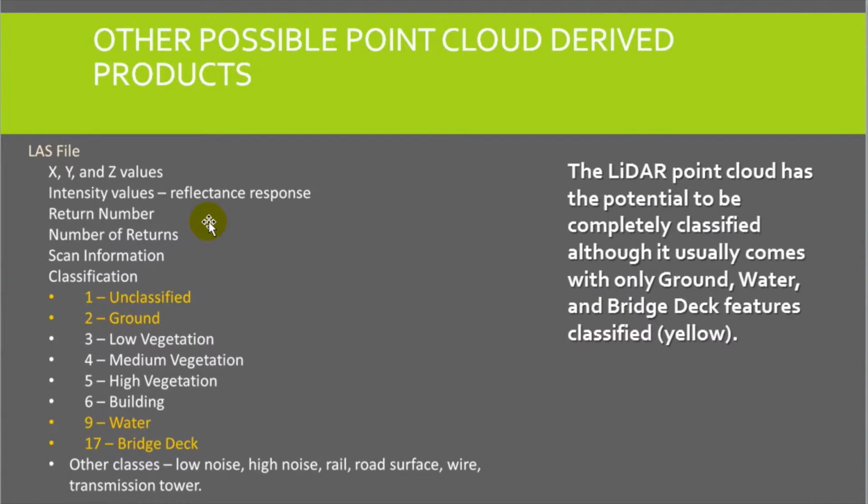When it hits a soft object, multiple returns can happen. If it hits a hard object, it's usually just one return. Each pulse that splashes back to the sensor is recorded with a certain return number. The most recent LiDAR data, what we call LAS data, or .LAS data sets, also lets each point be classified. Classifications can run a gamut of different kinds of things.